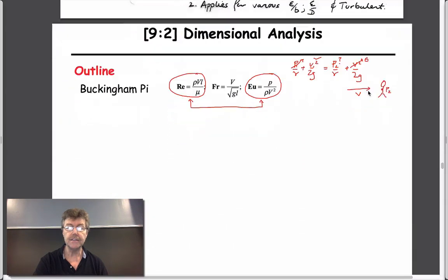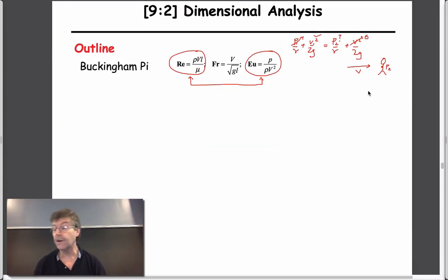The second is that if you're doing your experiment at the right Reynolds number, so you have exactly the right flow configuration, then you'd like to know something about it. And so typically what you want to know are the forces that are applied to the structure. And typically the forces are given by taking, if you're a medieval knight, then the forces on this shield are just going to be the pressure times the area, which is equal to the force. And so this pressure term here, if you know what area it's applied over, gives you a force as a function of the velocity squared.